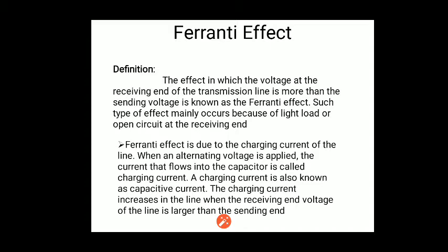Today we will discuss the Ferranti effect for a transmission and distribution system. We will discuss what the Ferranti effect is. Normally in a transmission line, the receiving end voltage is less than the sending end voltage due to the voltage drop and voltage losses in the transmission line. But in the Ferranti effect, the receiving end voltage is more than the sending end voltage. So this effect is known as the Ferranti effect.